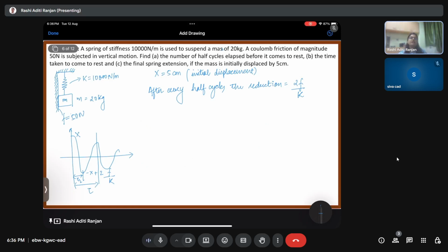The first question is, when is it going to come to rest? See, for a spring mass dashpot system, when we consider viscous damping, it will come to rest when some equilibrium condition is reached and all the transient is damped out, right? But this is not the case because there the damping force was C into x dot, and it was acting in the direction opposite to the stretch, in the direction of the inertia only. Here that is not the case.